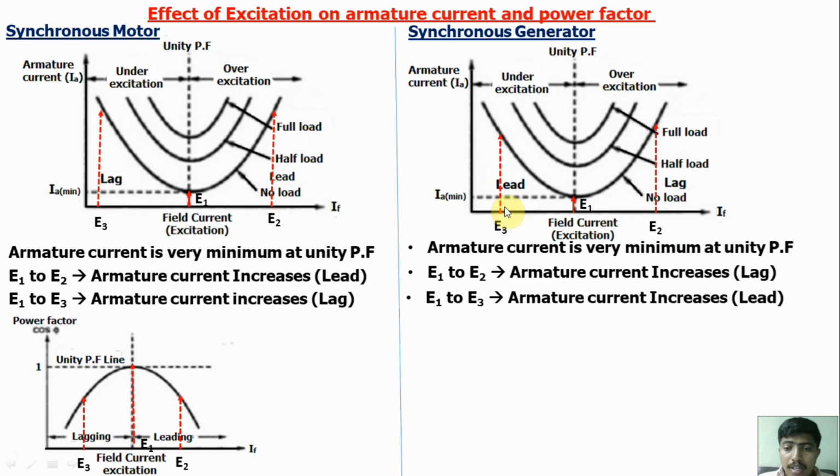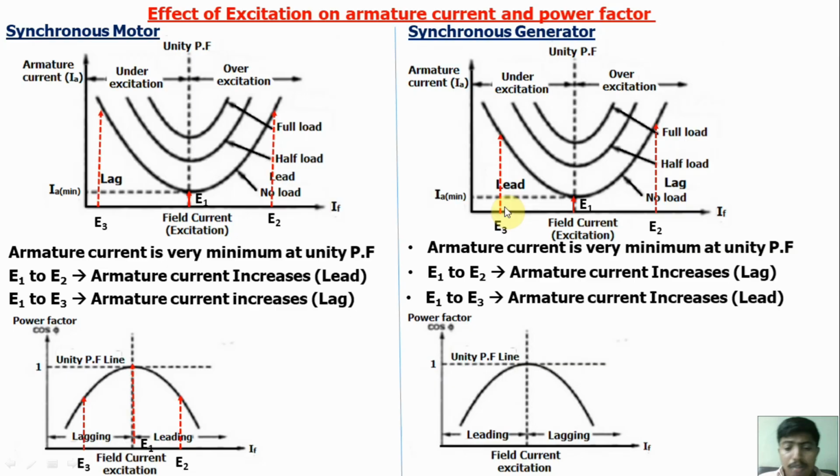Next, the power factor curve is a similar curve, the inverse U curve. The power factor will be maximum at unity power factor and decreases when the excitation increases or decreases. Now we will give the justifications for the characteristics.